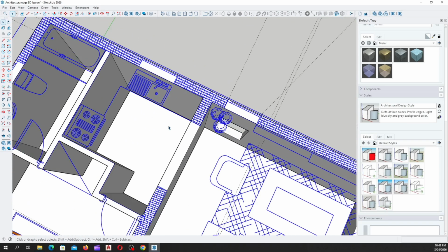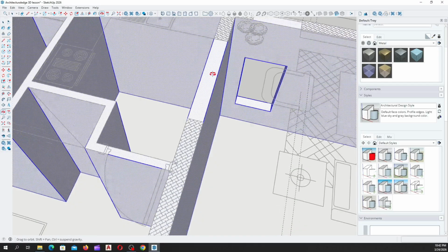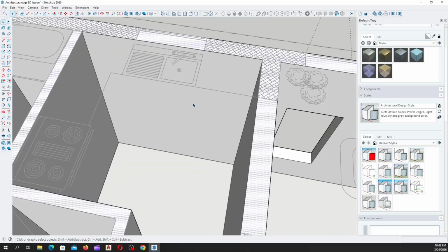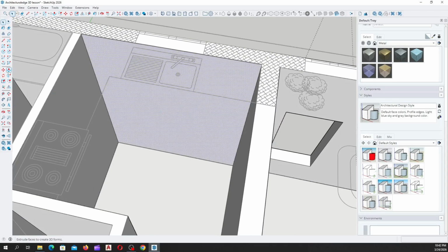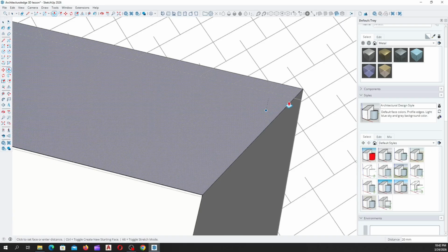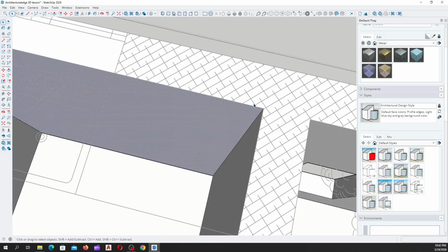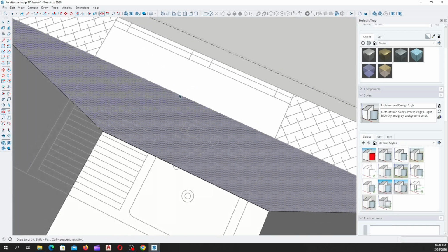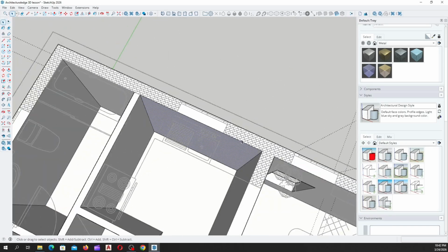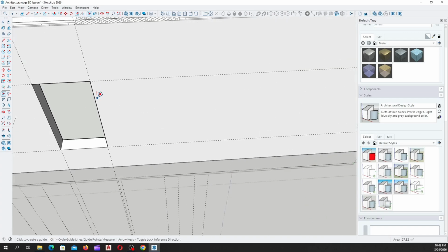So all right, how am I going to correct this? I'll just click in to access my wall group. Then I'll pick my push tool. Then I'll push this and snap it at this point. You see? Snap it at this point using our floor plan as the reference. So now let's go back out to try it again and see what we get.